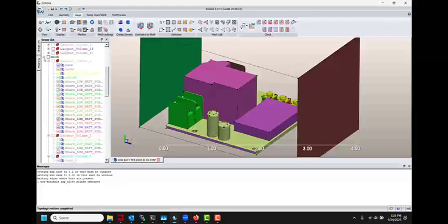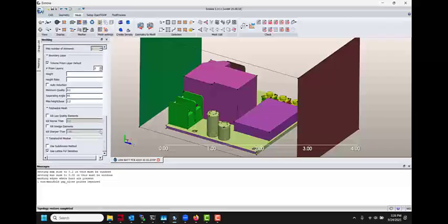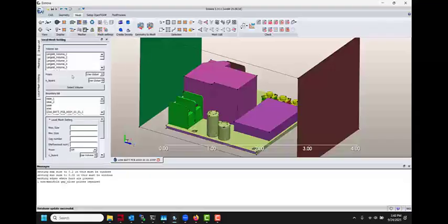The next thing is to finish off the volume mesh. You can do that from the global controls. So I'm just going to do 5 prism layers, and I'm going to have the first height around, say, 0.0025 inches. And those are the global settings. We'll have a look at what that does in a second. We also need to tell Ennova which surfaces in our model we want to grow prism layers on, which ones are going to be the boundary layers important to us. We do that with this local control.